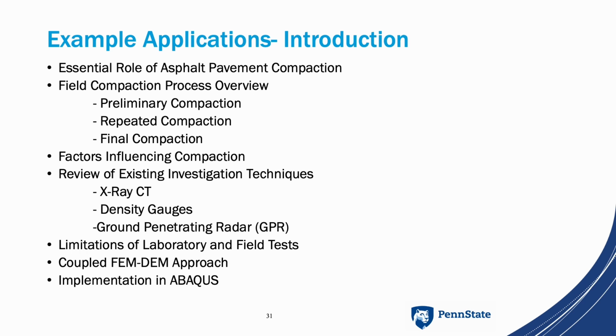In order to monitor the interaction between the material and the paving equipment, a modeling methodology was developed in the study through a coupled FEMDEM method. The general-purpose FE software ABAQUS, I think it's pronounced as Abacus, was used for the modeling. FEM was used in larger areas of the simulation, in this case the pavement base and the paver, and the DEM in smaller, more localized areas. Here was the asphalt mixture component. In particular, each DEM particle representing an aggregate in the preliminary compaction was modeled with a single node element.